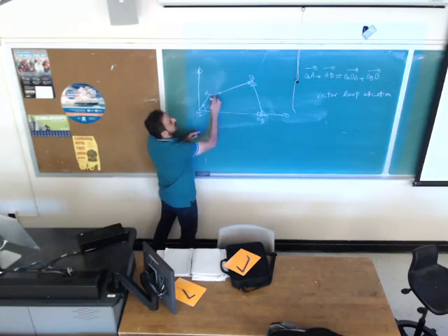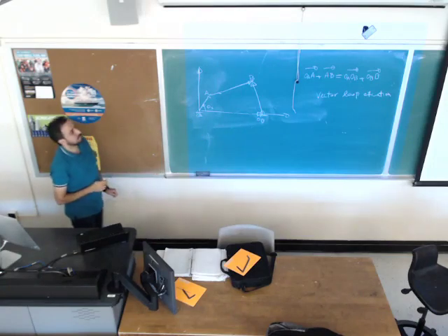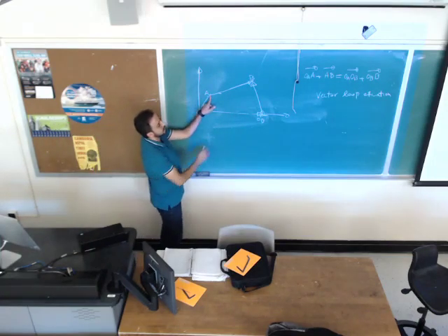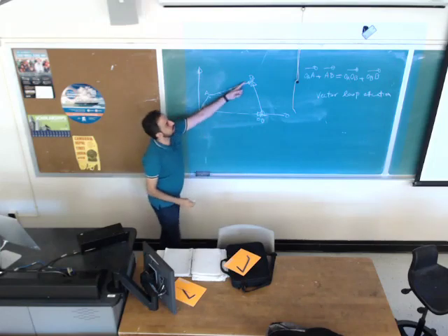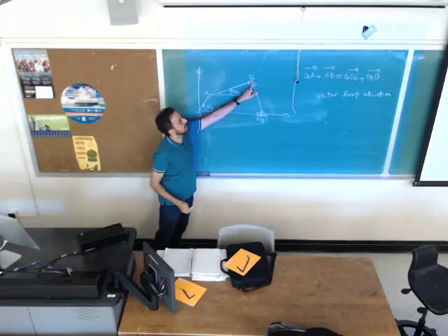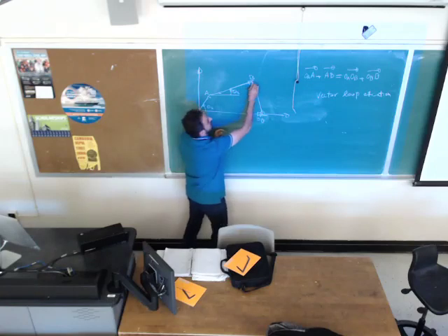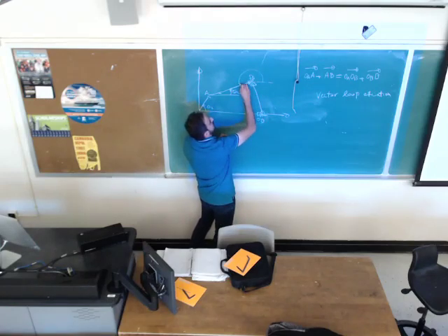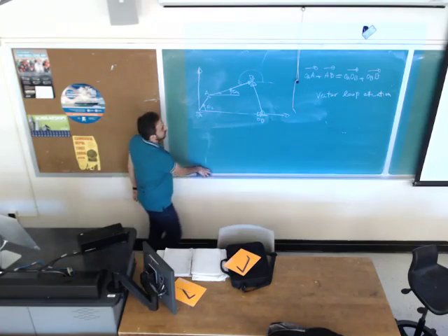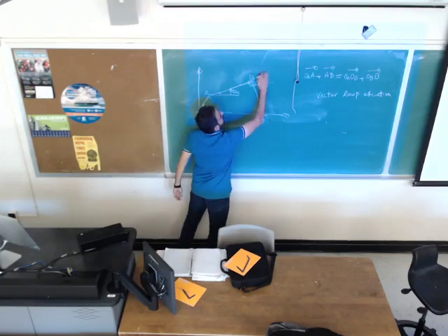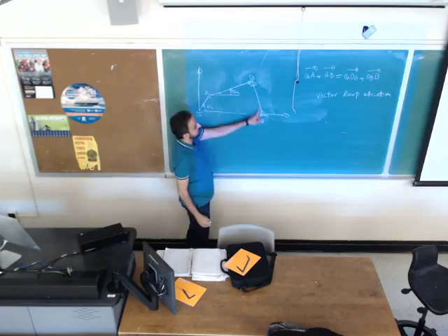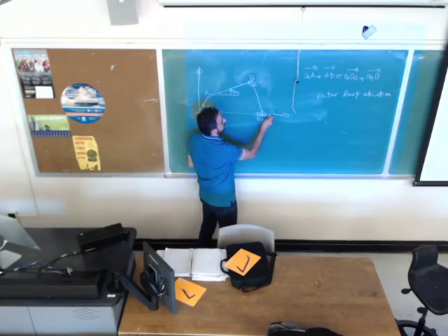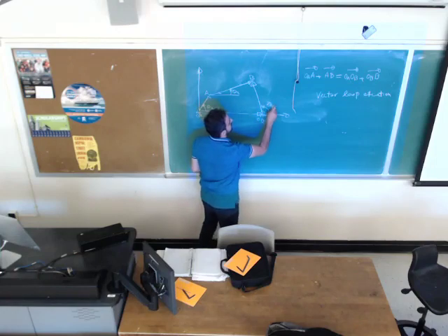For link 3, the starting point of the vector is at point A, so I'm going to measure the angle at point A and not point B. If you chose point B as a starting point, then you have to measure theta 3 at that point, but it's not happening in this case. For theta 4, the starting point is this one, so we label this at this location.